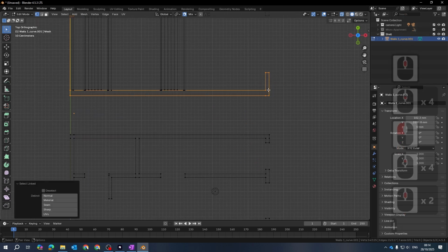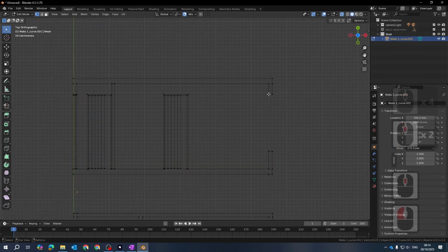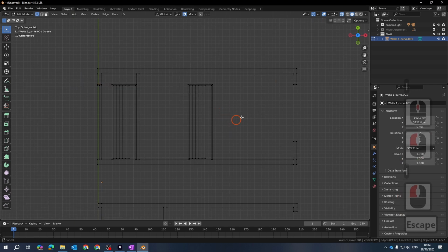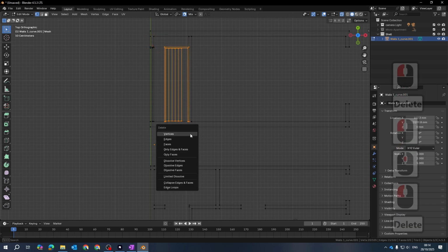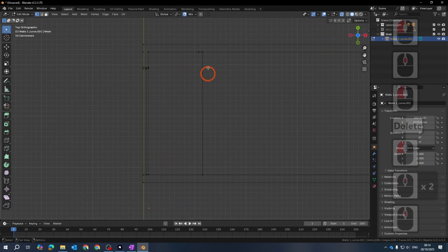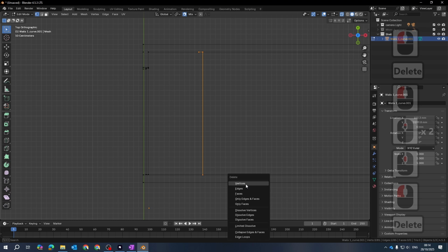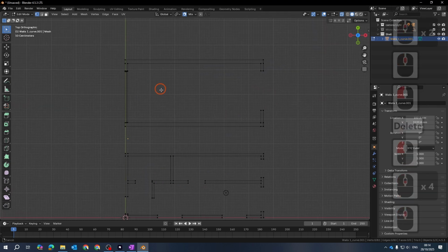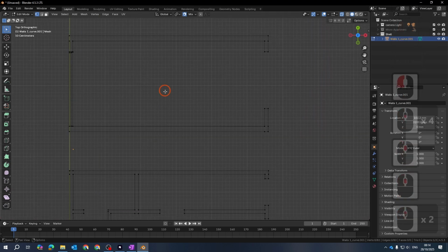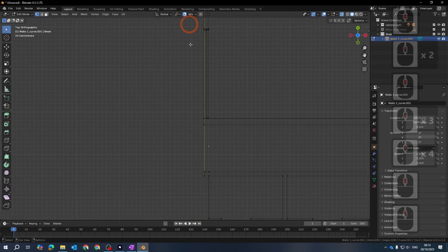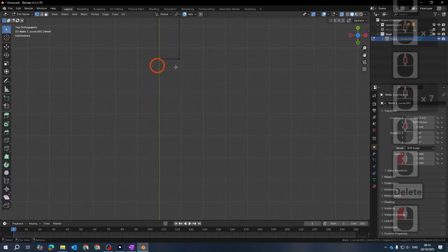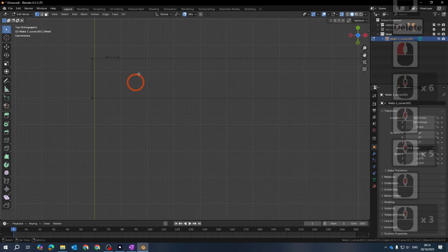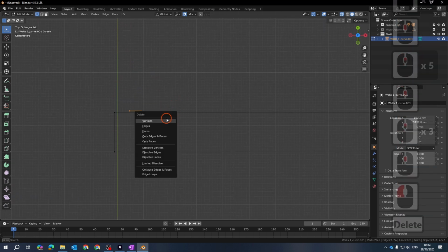And if I go link here, you can see it's linking all the right information. Okay, there is some redundant information that we need to get rid of, but it's something that we'll sort out later. So I don't need those vertices anymore, and I don't need those vertices anymore. Doesn't matter if we lose some information, because the plan will help us. I'm just using this as a height for my windows and doors. That's all I'm going to do with this information. I've got a door frame here, so I can maybe get rid of this information, delete those vertices. Okay, the rest I'm happy to keep.